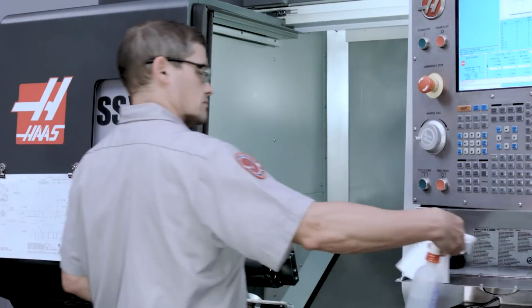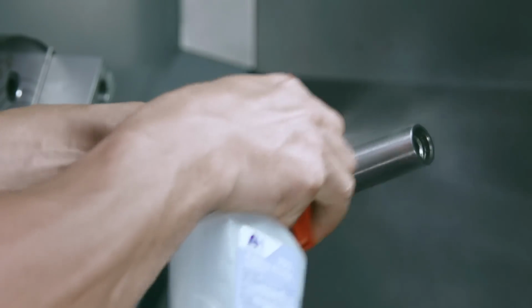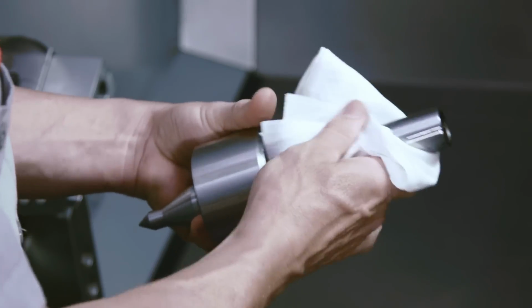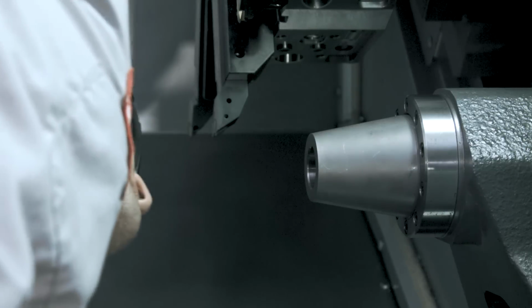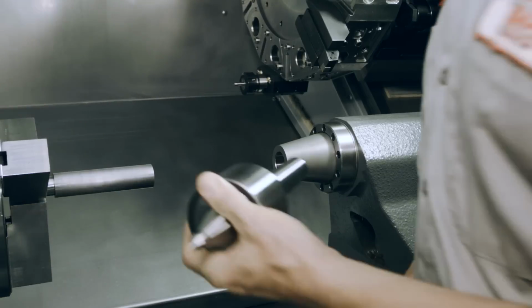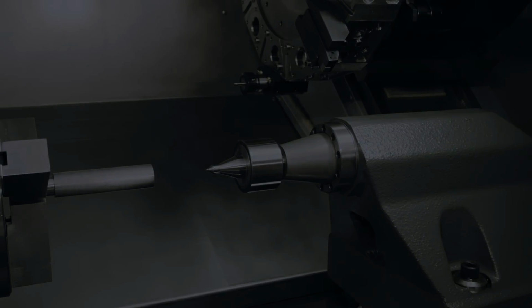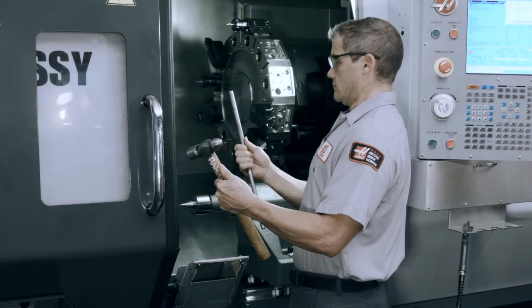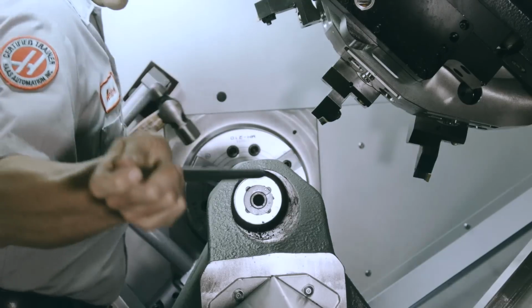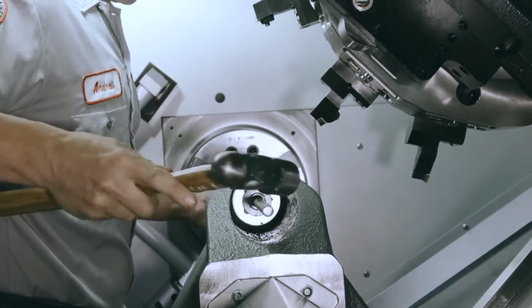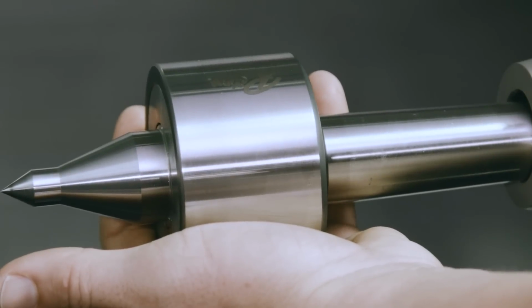Make sure that the tapered side of the live center is clean, rust-free, and has no dings or other damage. Visually inspect the condition and cleanliness of the taper in the tailstock as well. There should be a perfect sliding fit into the tapered tailstock bore. The correct method for removing the live center from the tailstock housing is, of course, to use a steel drift and hammer to break free the taper's tight fit. A badly stuck live center is rare. If it does happen, contact your local HFO service rep.